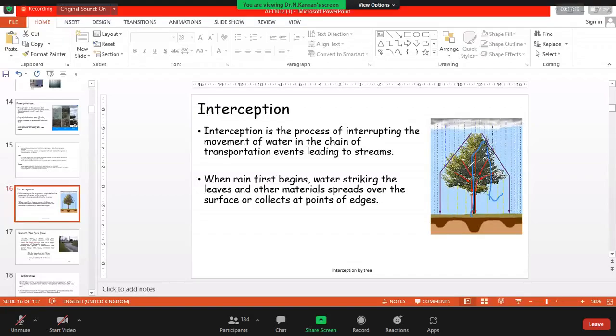Most of the people are talking about soil erosion. You know that? Soil erosion is the process of detachment and transportation of soil particles from one point to another point by different factors such as moving water, wind, and man-made activities, right? So when you get this rainfall touching this soil directly, if you get no vegetation here, it can make more soil particles detached from their parent materials. When you have enough water on the surface, if it is moving, the detached particles will be taken by this moving water. So it induces the amount of soil erosion. You got the point?